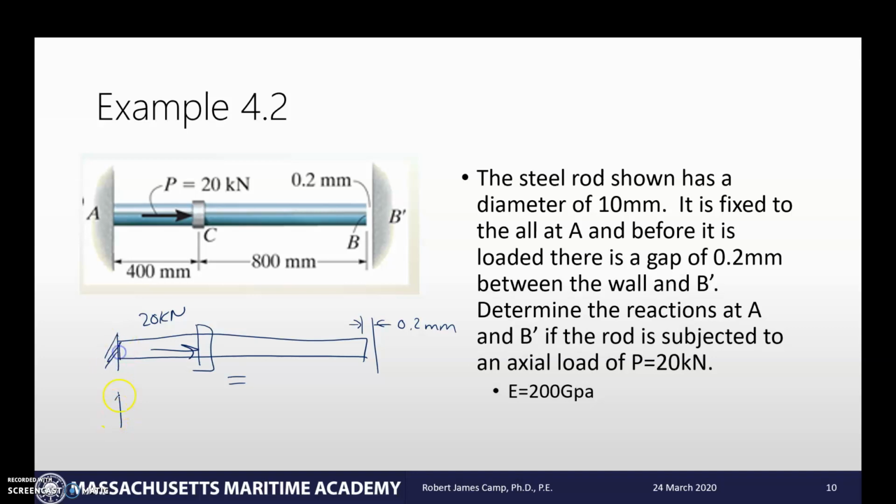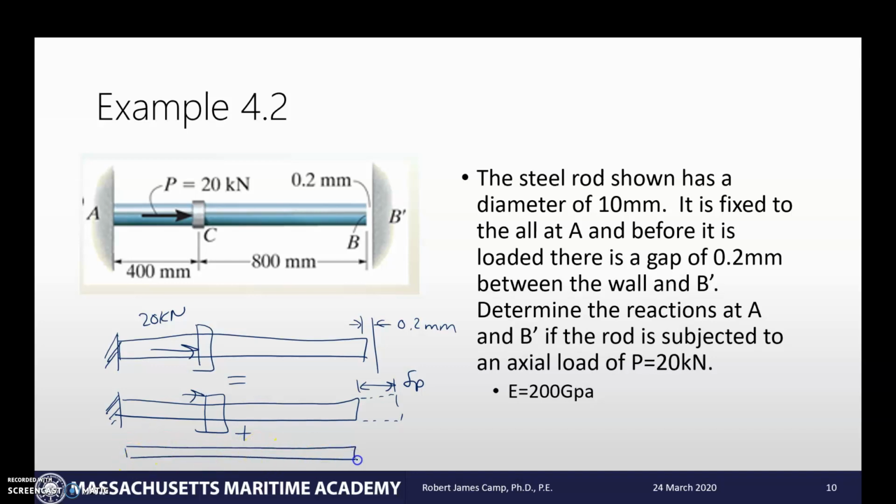So the first thing we're going to say is, okay, I've got this rod that I'm applying this load onto, and it's going to deflect. It's going to deform by some amount, delta P. Now I'm going to take that situation and add to it this situation here where I just have this bar that I'm going to apply a force, FB, to push back on it.